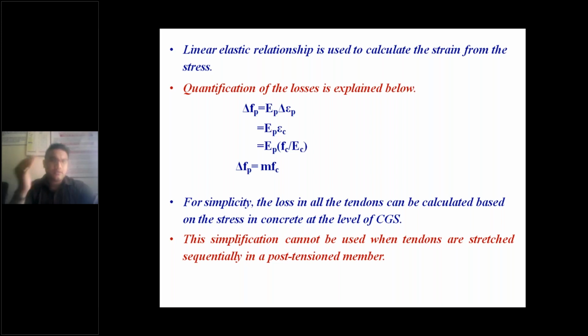See, for this you have to go back to your strength of materials subject. I told you in unit 1, when you had this concept called composite materials. When you are calculating the total strain and total stress of a composite material, how do you calculate it? When the composite member is subjected to load, what happens? When it is subjected to load, there will be an equal strain. Let us take a composite material of steel and concrete, right?